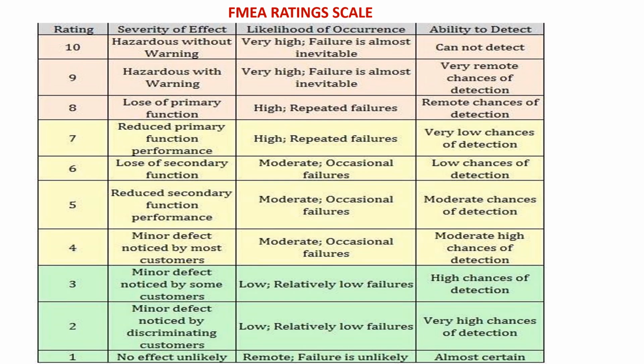The risk priority number is a factor which is a multiplication of the severity number, the occurrence number, and the detection number. It will always be between 1 to 1,000, and the lower the number, the lower the risk. The higher the RPN number, the higher the risk.